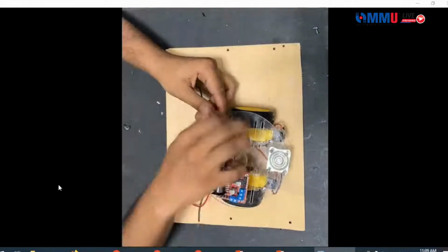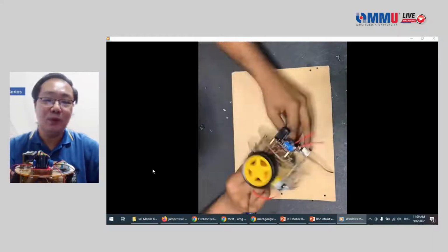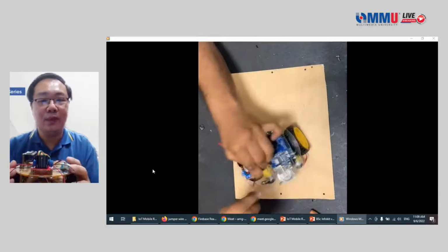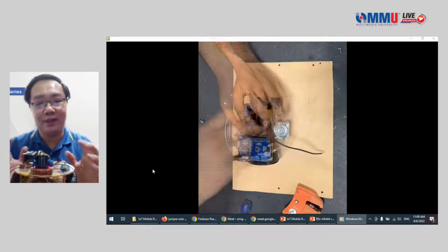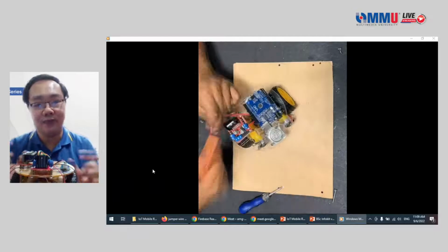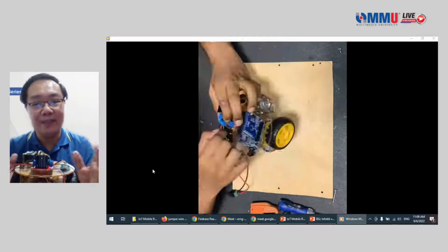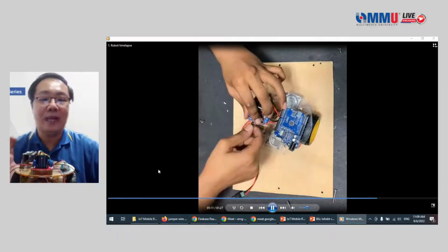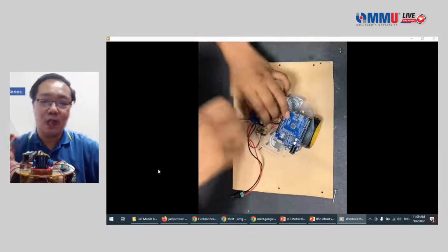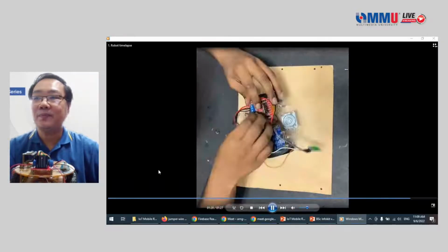also our microcontroller. In this video, we are showing you the assembly using an Arduino Uno and a DC motor driver. But of course, in this IoT robot, we are going to change the Arduino Uno into the NodeMCU, because we will need the Wi-Fi capability to connect to the internet. We will use a public IoT server called Google Firebase. It is a real-time database, so we will use that database to store our data and also to store the control commands for this particular robot.